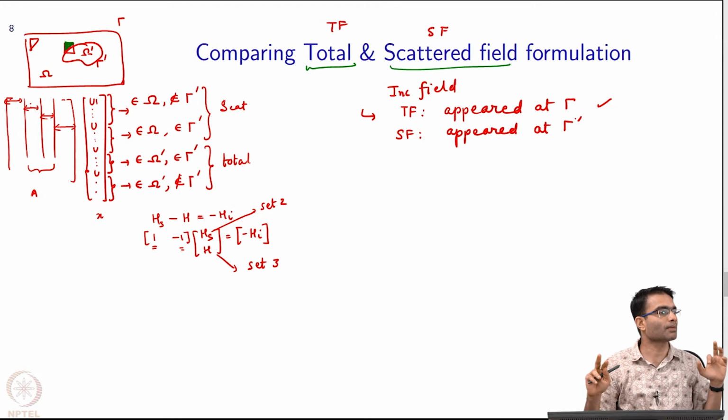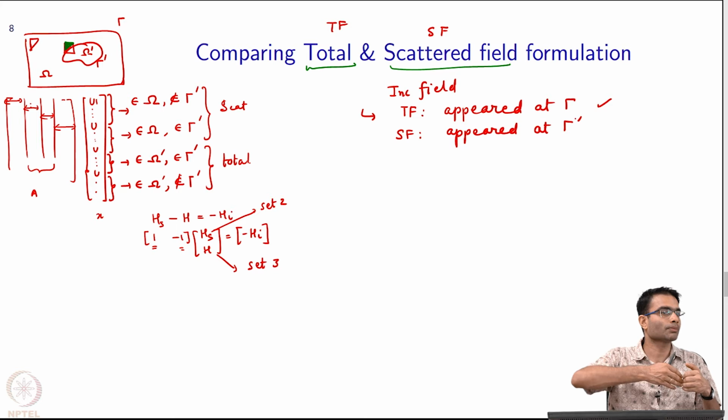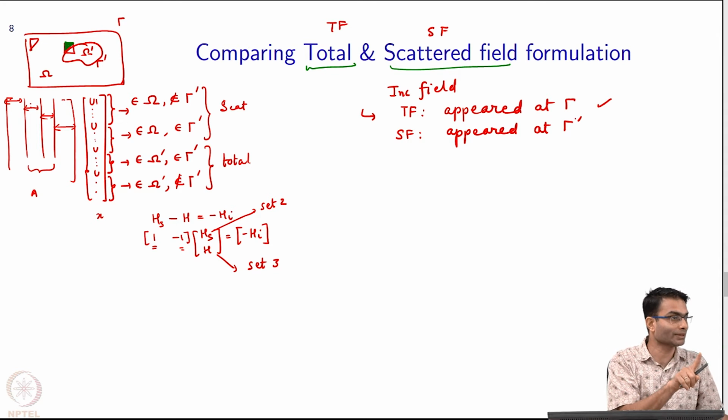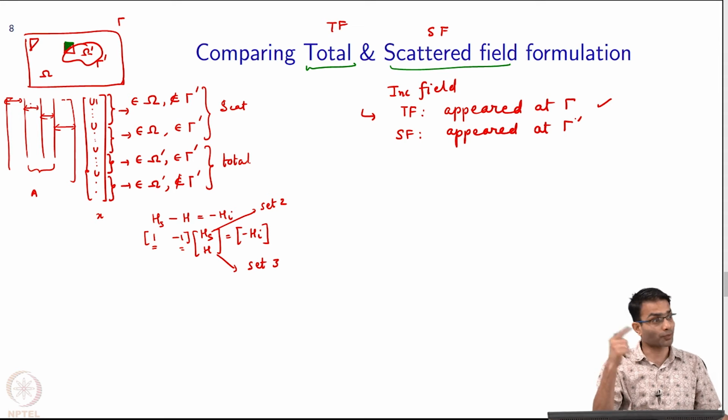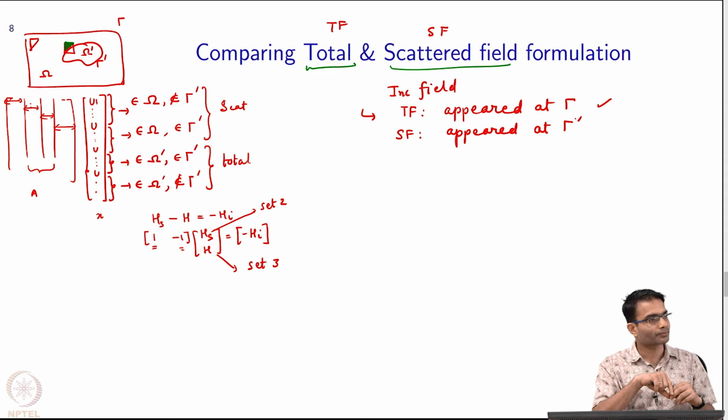You will get the same answer as you make the discretization finer and finer, because the variable is being expressed on the basis functions of those triangles, right. Those triangles you saw were linear in x and y, but the actual field is what? Exponential, sine and cos. So, I am approximating sine and cos by linear functions in x and y. That approximation gets better and better as the size of the triangles is made smaller. Sin x becomes x, cos x, whatever other approximation you want to do.